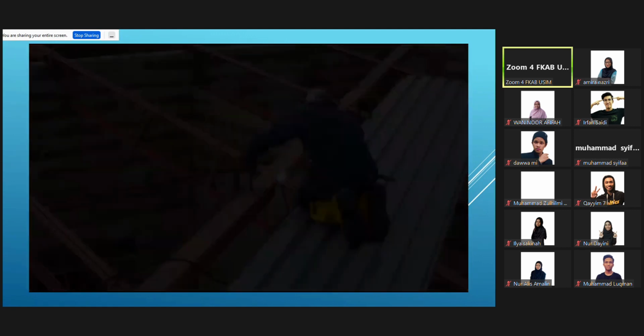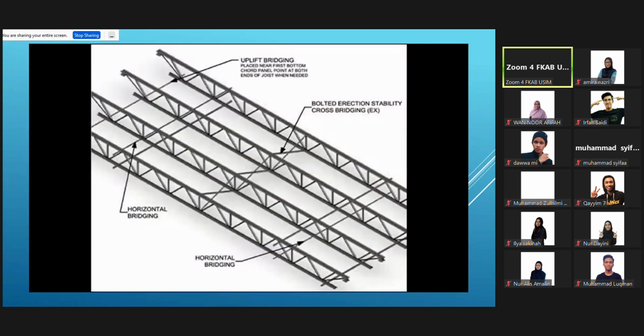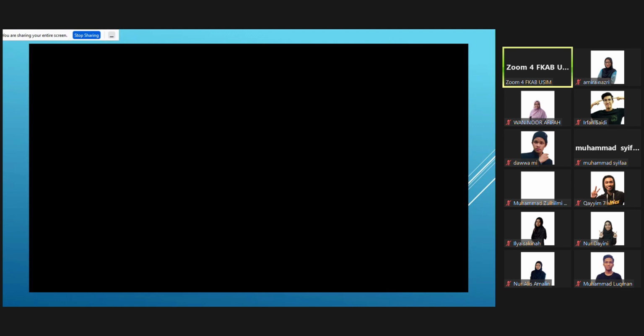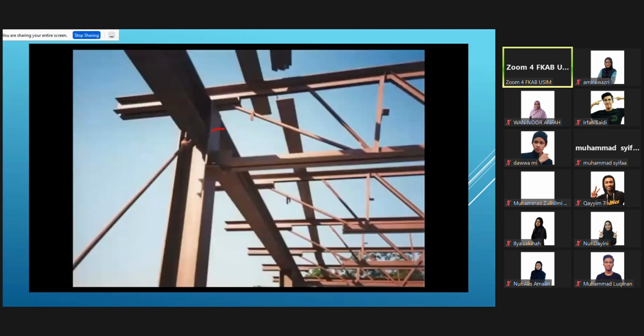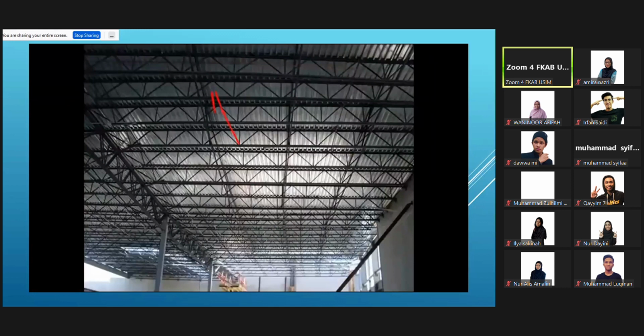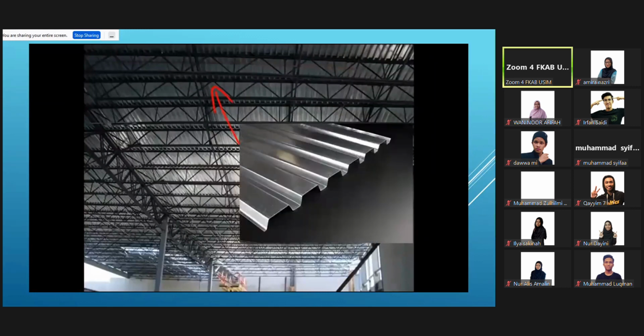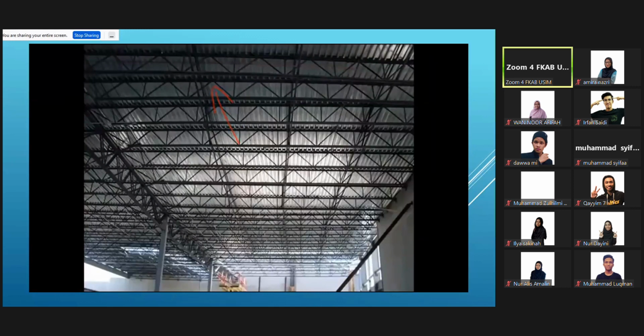As the joists are placed, lateral bracing is installed from joist to joist, which links them together, creating a total system. Now, installation of the bar joist does not complete the framework of the structure. Although the connections have been secured, the frame still has the ability to move out of square. To eliminate this tendency, a corrugated metal deck is installed on top of the horizontal framework.